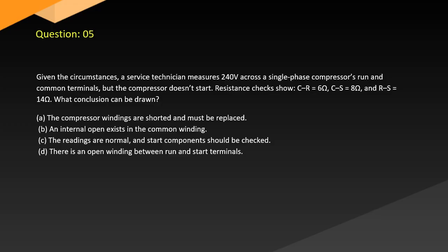A. The compressor windings are shorted and must be replaced. B. An internal opening exists in the common winding. C. The readings are normal and start components should be checked. D. There is an open winding between run and start terminals.